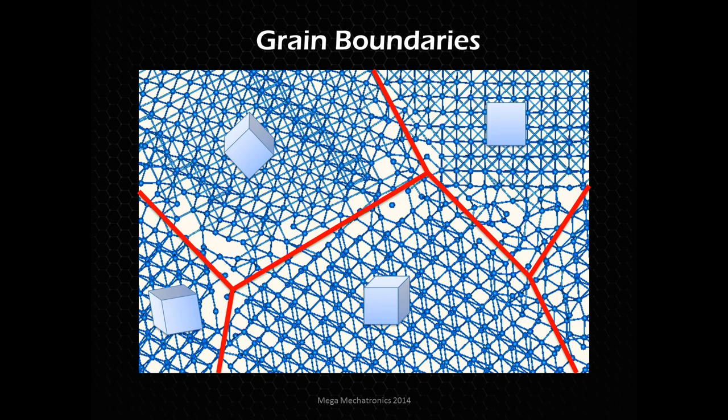If you have smaller grains, more smaller ones, that's going to give us a stronger, harder material, because we're reducing the ability for that crystal lattice to deform and move around, because there are these deformities there, sort of like a wall stopping them from moving any further.